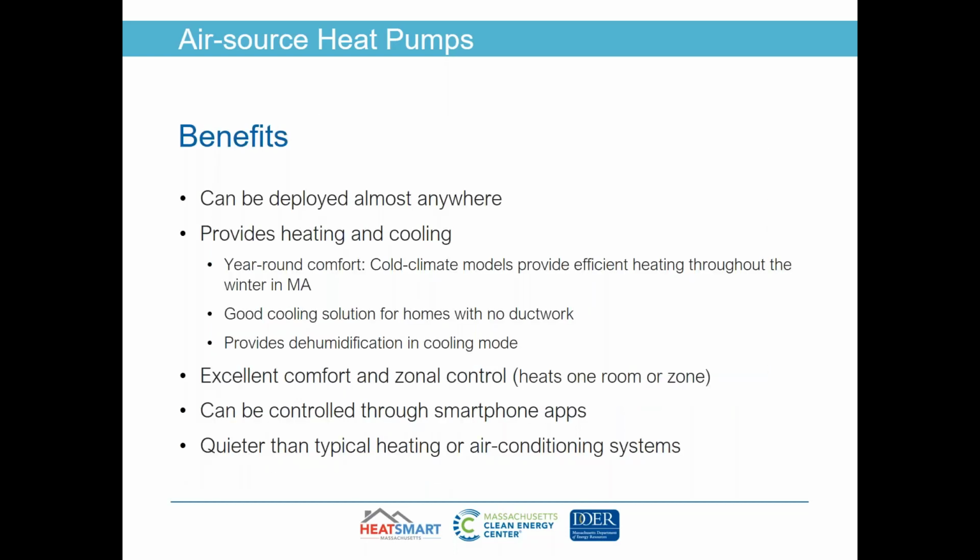Now, the benefits of an air source heat pump, first of all, they're very versatile. They can be deployed almost anywhere. They provide both heating and cooling depending on where you are in the season. So the cold climate models, again, can provide very efficient heating down below 0 degrees throughout the winter. They're also a very good cooling solution, especially for homes with no ductwork, extremely efficient for cooling. And then they also provide dehumidification when they're in cooling mode. So they really provide very good comfort.